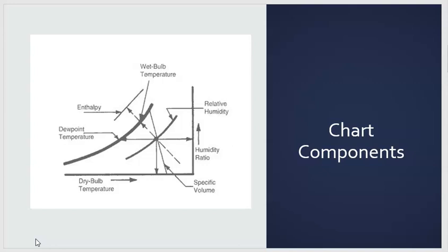This is determined by use of a sling psychrometer. On this, it's two pieces of a thermometer. One has a wetted tissue that goes over the bulb, and then you sling it in the air until you get the temperature.